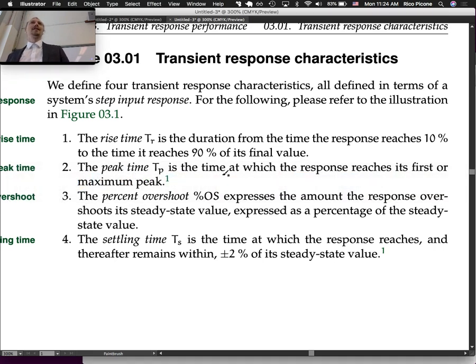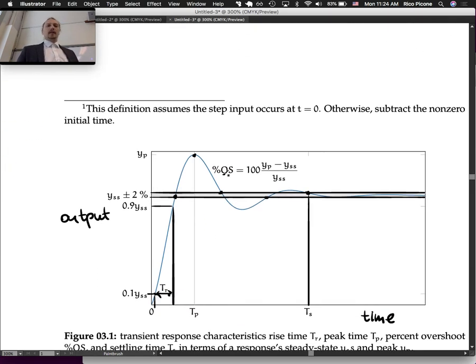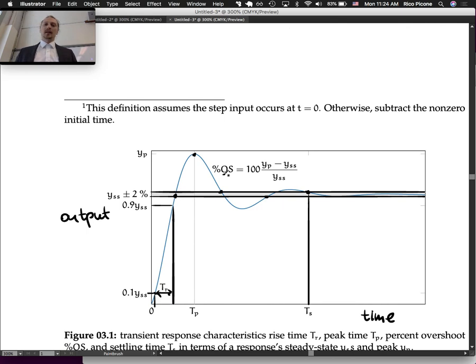Any other questions before we move on? How do these points on this map relate to, I don't know, the time constant of a system? Yeah, okay. So this blue line is just some system response. It looks like it's probably a second order system. I simulated it last year, so I think it's second order. It's underdamped, right? Because it has oscillation, but it goes to 0. It damps out.